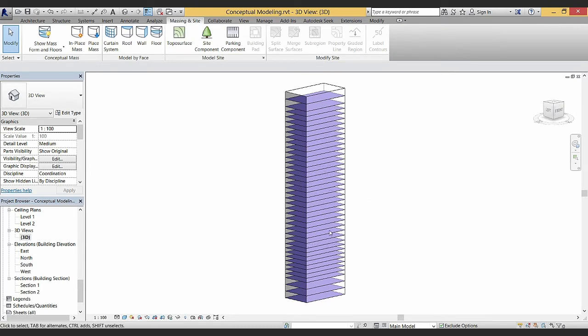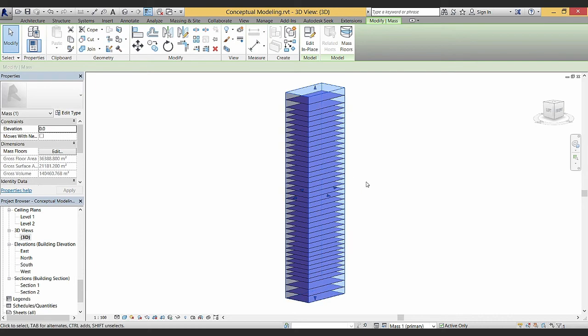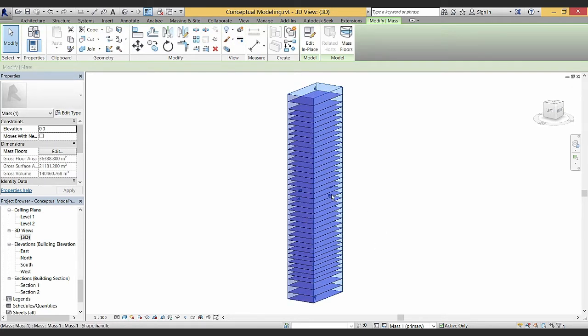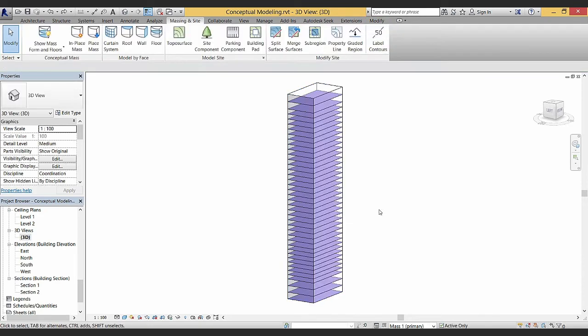I can't click on it unless you deselect the toggle button, exclude options, then I get access to it. Basically, this is meant to work like this. You change from the main model design option, which is like everything else, and then you select mass 1. Now, mass 1 is selectable. Everything that's in the option mass 1 is going to be editable for you. You can change it, drag it, do whatever with it.